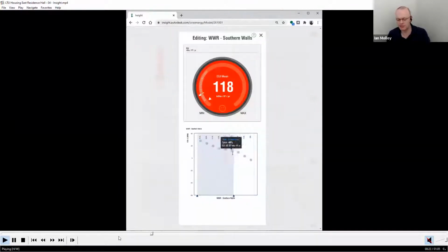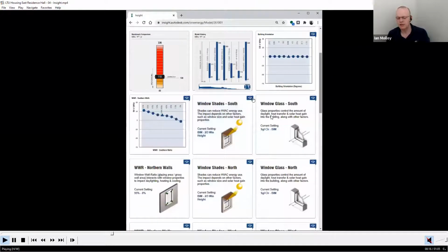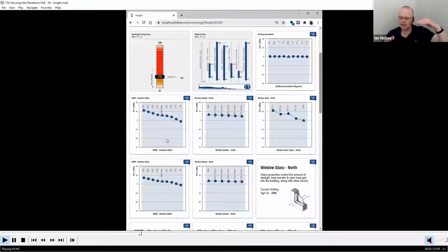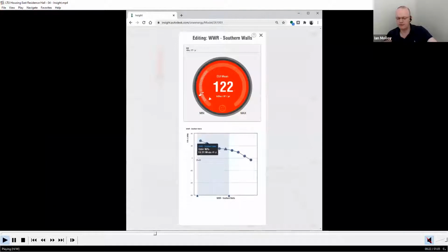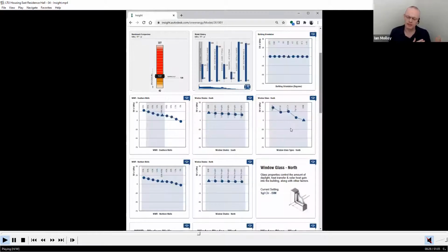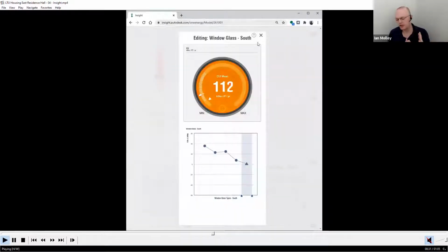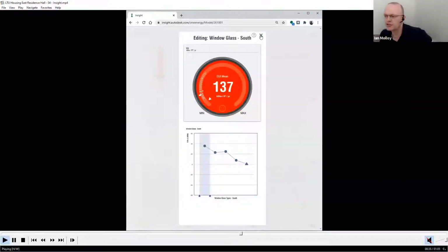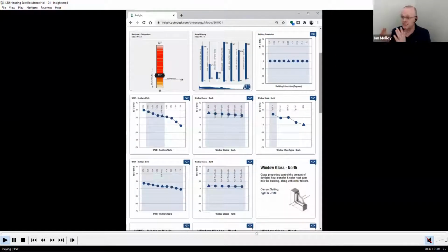So what this presents you with when you look at these scales is the relative sensitivities of the overall building energy to each of these factors. You can see the window to wall ratio on the south facade, as you would expect, is reasonably sensitive. If you increase the window to wall ratio, like go to 80%, you'll see the energy goes up. And if you reduce it, it goes down, right? So this is reducing the glazing type. And you'll see some really interesting interactions here. If you make the windows bigger, the glazing type counts more.